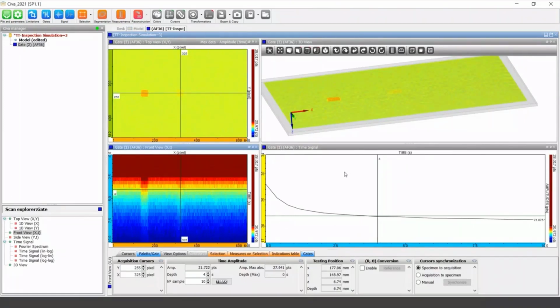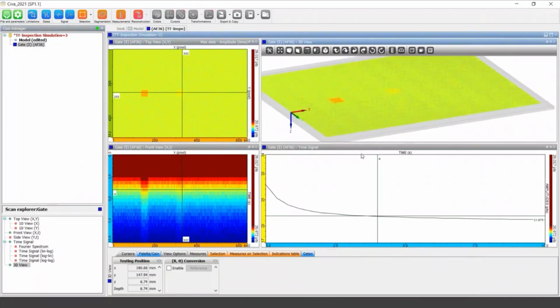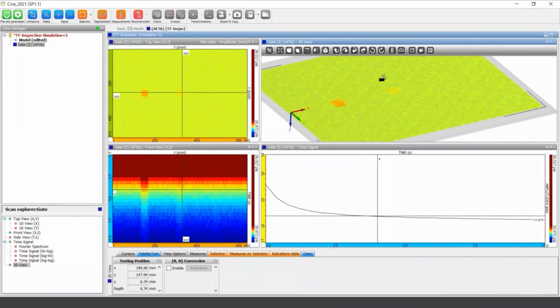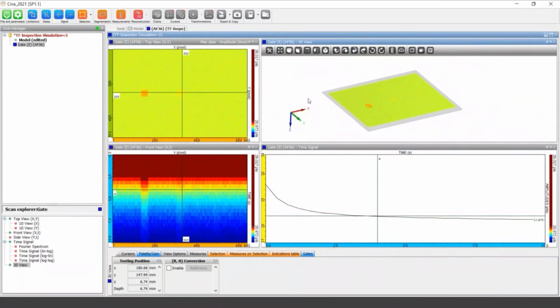Okay, let's mention also that this signal curve, for instance versus time in Cartesian scale, can also be available here in log scale. You have another image here. Also, you can take the FFT of this signal, and so on. So this is basically the results you obtain from this simple simulation, with 3 defects here. In this case, we were in reflection in a composite slab.